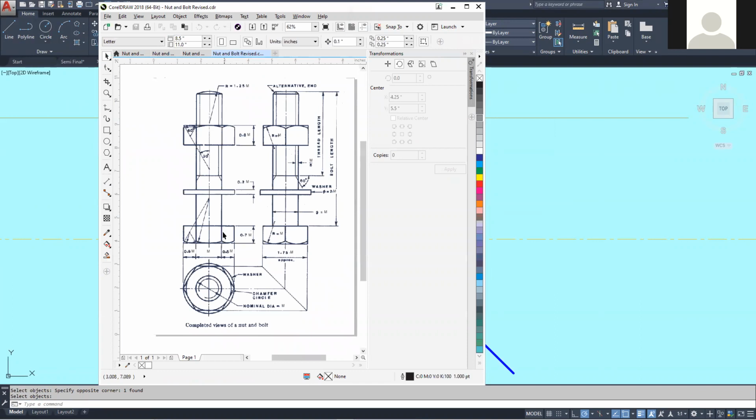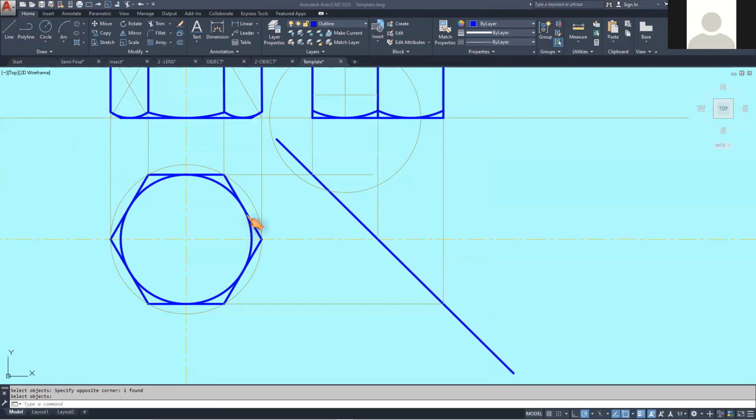As I was saying, in Trinidad they give you the size of the bolt, but for technical and mechanical purposes, once you are given the size of a bolt as M something, M10, M20, all dimensions would be done in relation to that. So from here to here would be 10. And to get the hexagon, you draw a circle twice M and put the hexagon in that circle. So once you have this hexagon here, that would be this light line here.